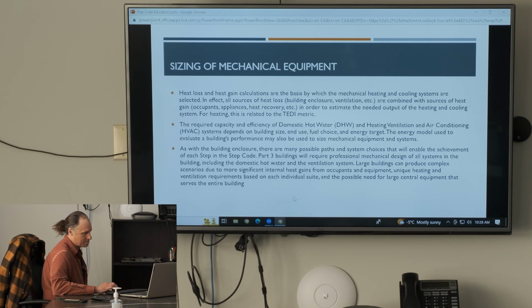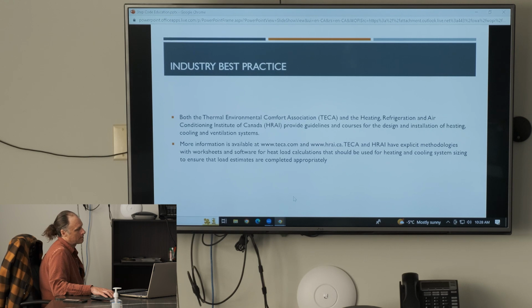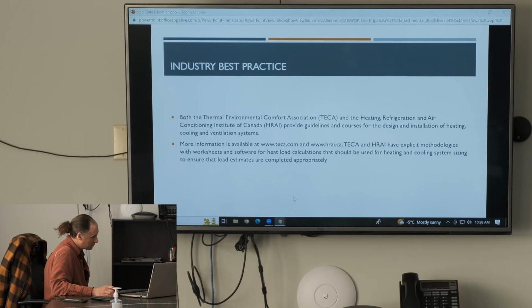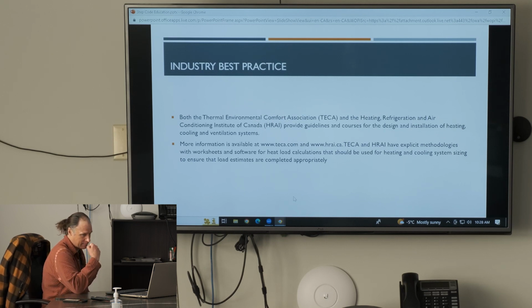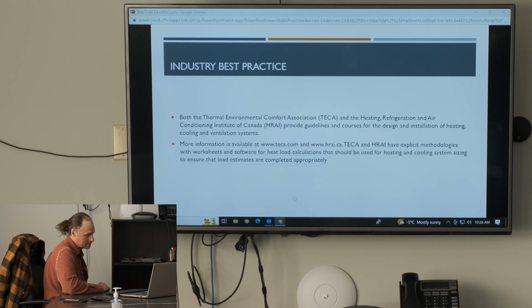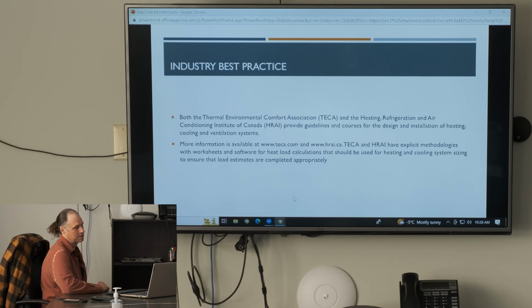So what's an industry best practice? Both the Thermal Environmental Comfort Association, TECA, and the Heating, Refrigeration and Air Conditioning Institute of Canada, HRAI, provide guidelines and courses for the design and installation of heating, cooling, and ventilation systems. More information is available at teca.com and hrai.ca. TECA and HRAI have explicit methodologies with worksheets and software for heat load calculations, that should be used for heating and cooling system sizing to ensure that load estimates are completed appropriately.